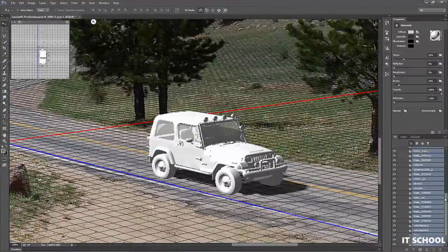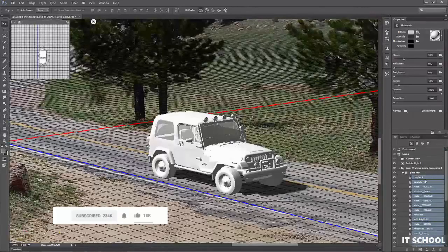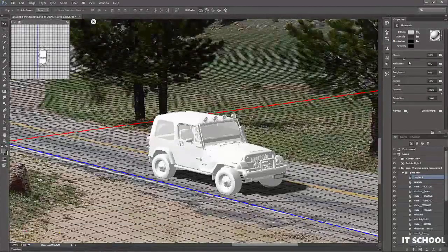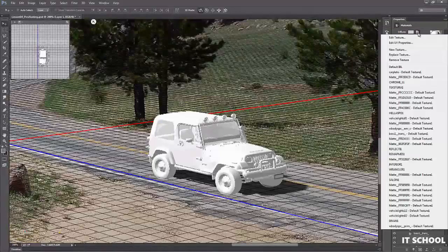And then the next thing that we need to do is go through and start realigning the texture definitions. Now as we select each individual mesh here, you can see the material that's assigned to it. And along the diffuse line here, we have this different little icon. This means that there's already a texture assigned to it. But that texture isn't lining up because it's still pointing to those original Targa files. So what we need to do is remap it to the JPEG files.